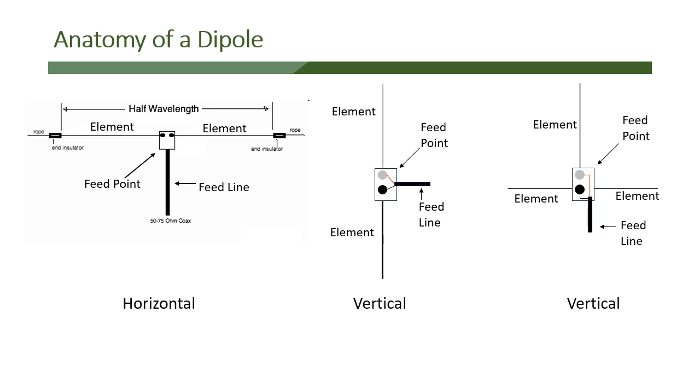Or if I have a handy-talkie, remember, almost every antenna has to have two parts: a left side and right side, or a positive side and a negative side, for lack of better terms. When you have a handy-talkie, there's only one piece of the antenna coming out of it, and that's the vertical. So where is the other side of that antenna? It's you. When you touch that handy-talkie, you become the other part of that antenna. It's not that handy-talkie antennas are not very efficient. They get the job done for what they're designed to do, and you become the return element in that signal path.